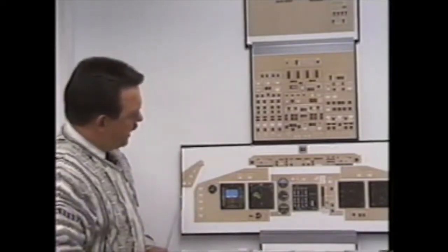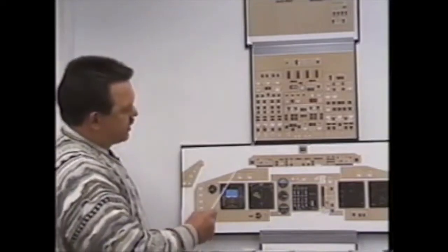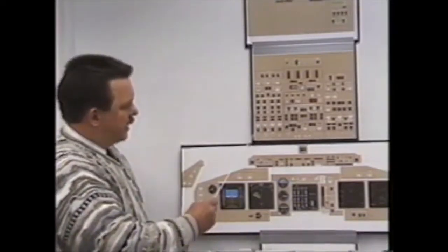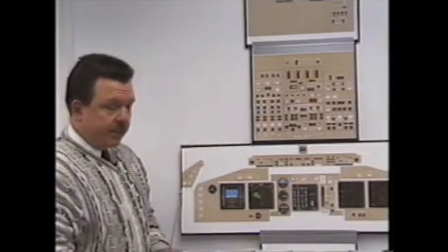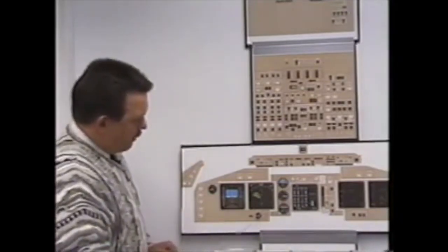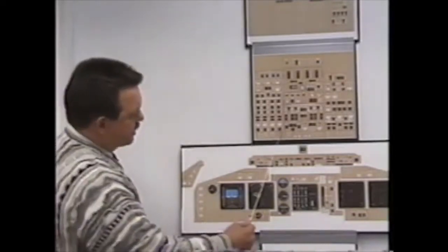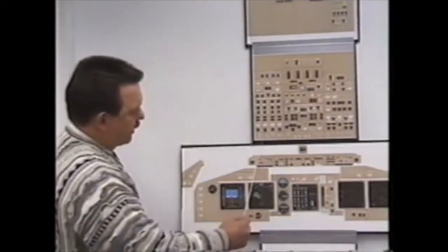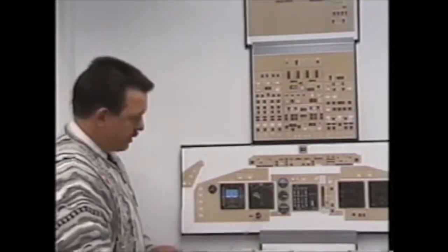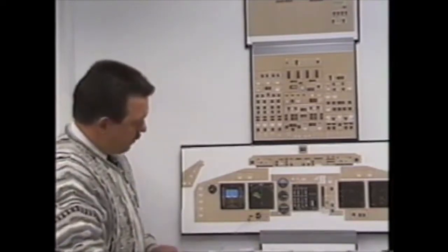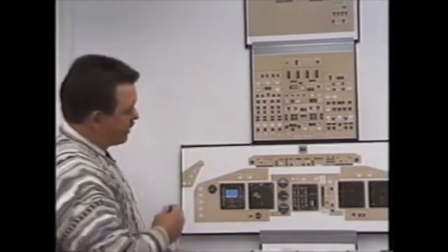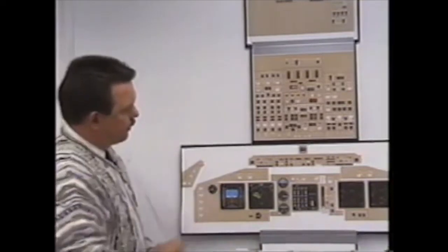Brake source light is illuminated, and I reach up and pressurize System 2 hydraulics with the air demand pump. System 2 is pressurized. That will not bring up the brake accumulator gauge. The brake accumulator gauge is in System 4. System 2 pressurizes the alternate brakes. As a result, it cannot bring the gauge up. The brake source light is out, though, indicating that brakes are available on hydraulic System 2.